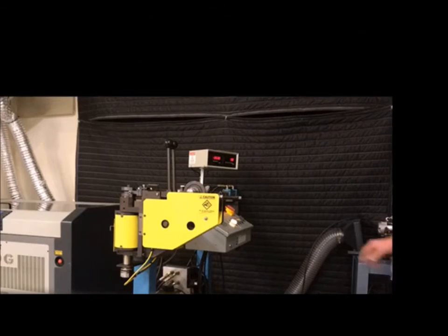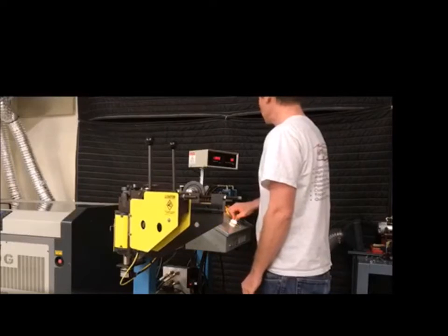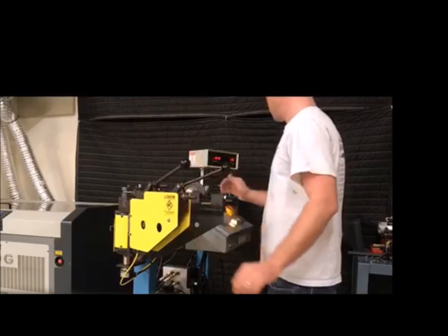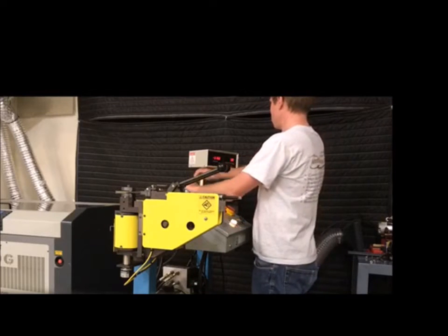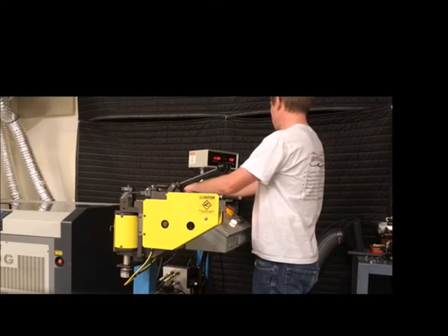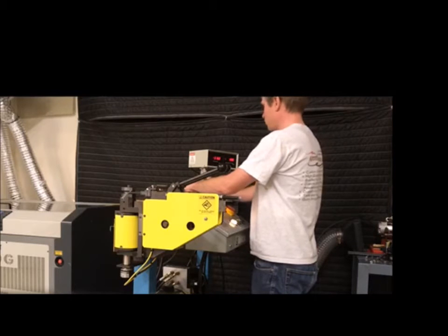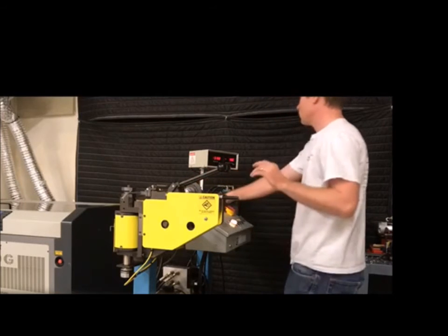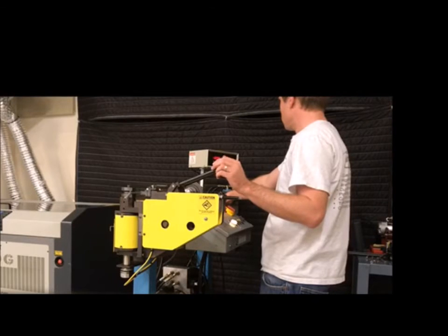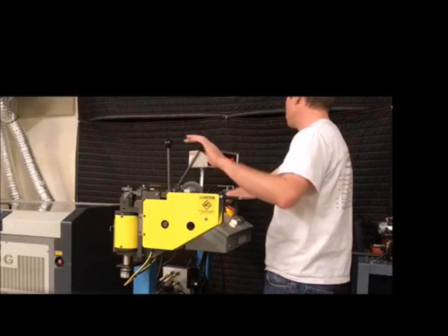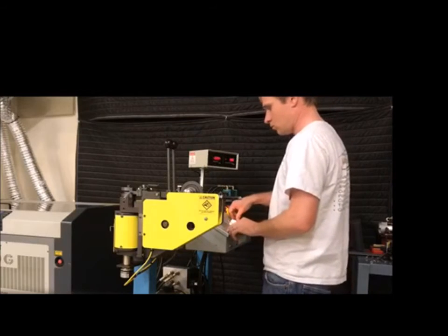So what you'll see right here is this is our tubing bender. It's a computerized tubing bender that has digital readouts on all axes. We just made our first bend, and now what we do is we move the tubing using that two-dimensional sheet that we have. We move it to a specified X and Y location, and once we've moved to that specific location, which can be seen on the digital readouts, at that point we go ahead and we clamp the tube back against the die, which is happening right now, and then we make the second bend.